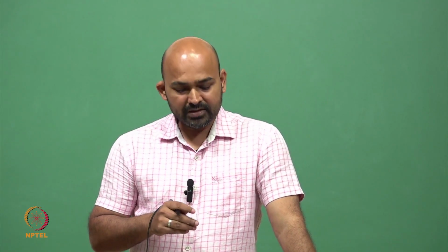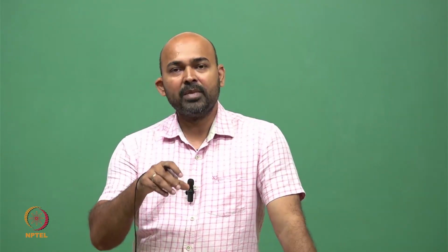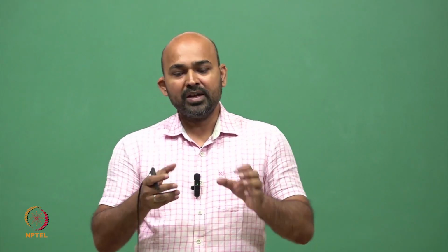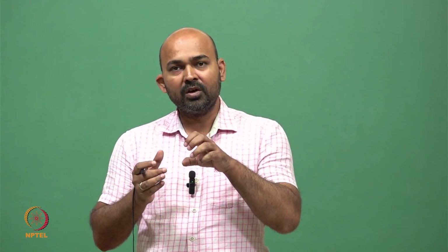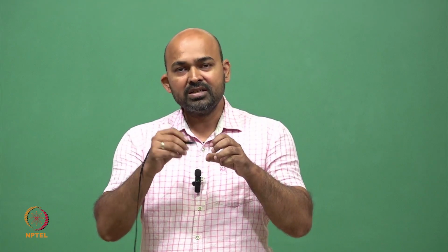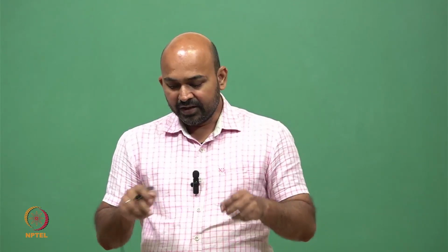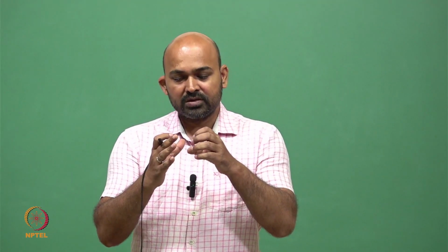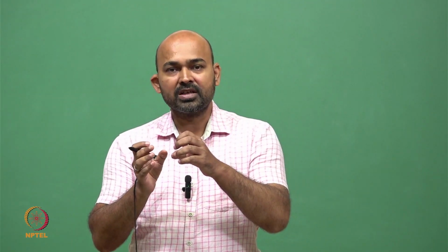One point to note in the case of yoke coils: because we are relying on the magnetic property change of the shaft, the yoke coil needs to be placed in very close proximity to the shaft, so that the change in the magnetic property significantly affects the flux linkage of primary and secondary. So we need a closely placed yoke coil for accurate measurements.